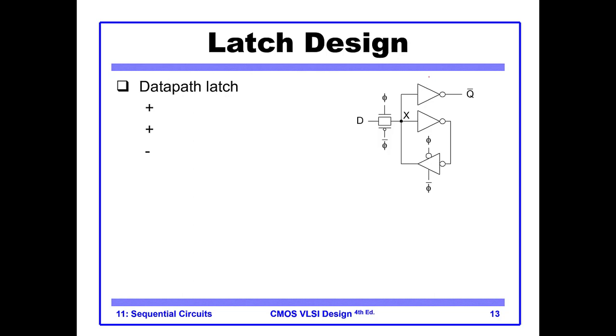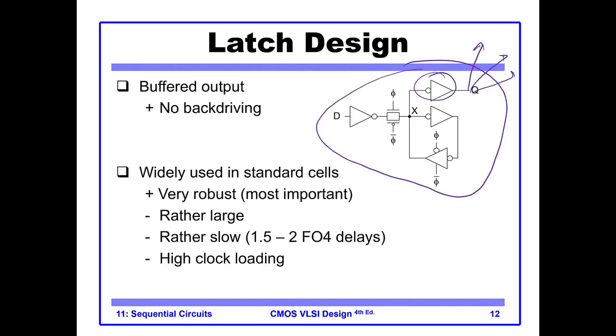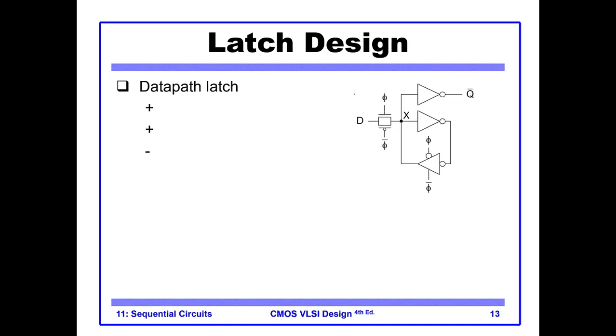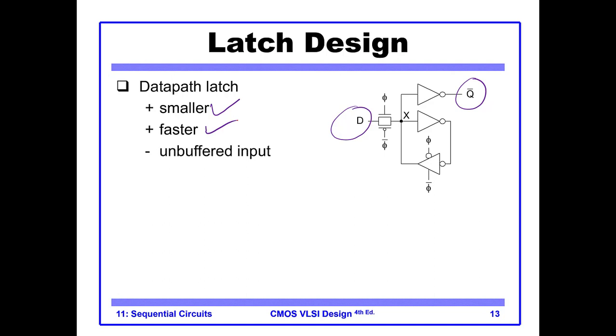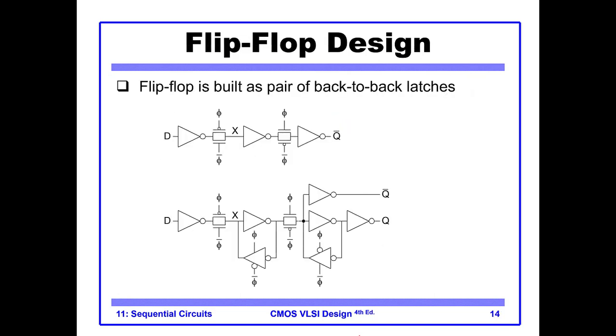Another design is where we don't have the inverter here at the input, so the output is inverting. The advantage of this one is that it is smaller and faster. The downside is that the input is unbuffered, so you have inverting outputs.